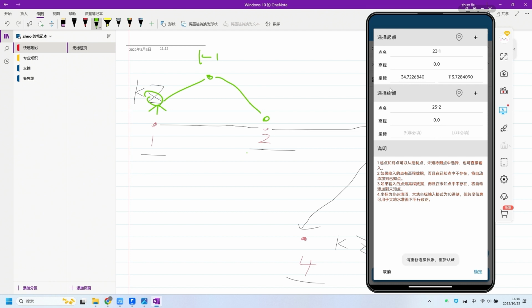If you don't need to correct it, you don't need to collect it. The interface will also tell you that this is not a mandatory field, but if you want to collect data, you must go to the control point and collect an actual longitude and latitude of it. Don't fill in the longitude and latitude of the measuring station, and don't fill in the same values for the two places. Just observe both sides directly at the location where I set up the instrument. Don't do this, make sure to observe.